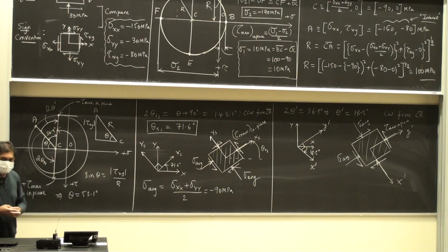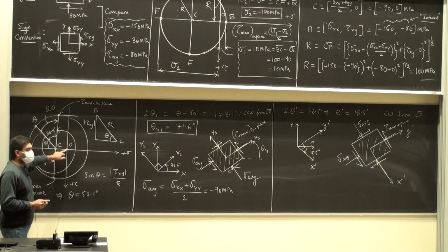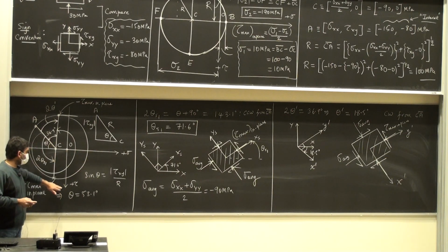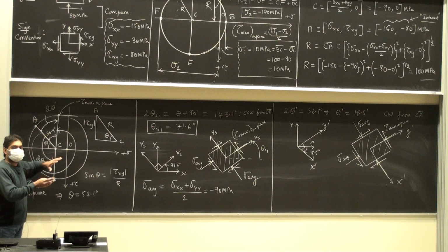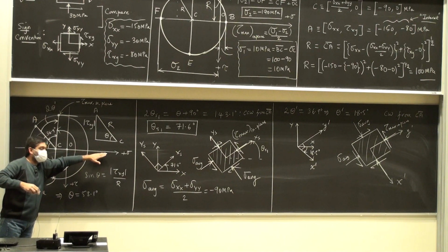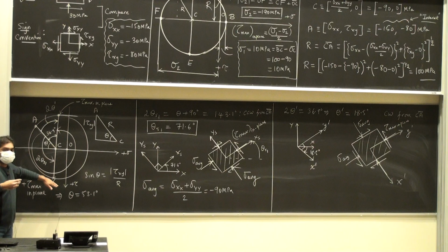Yes. For problems like this, do you theoretically have the freedom to go ahead and move your axis? Move my axis, you mean this point? Yeah. I mean, you got to start off with an origin, a coordinate origin. And typically, if you're using Mohr circle, this is the convention: positive sigma here and positive tau there. If you're going to use Mohr circle, you have to be wedded to the fact that this is positive sigma and positive tau. That cannot be changed.